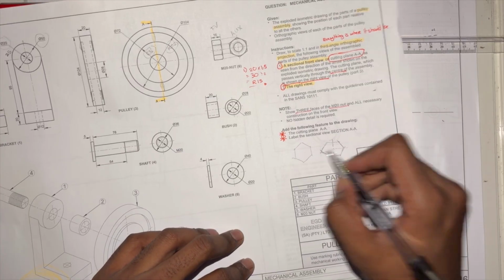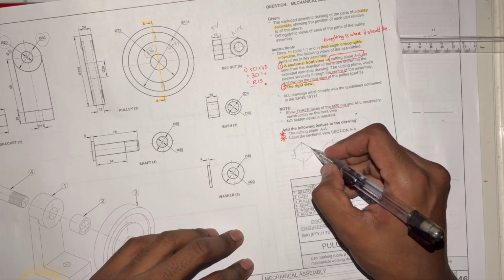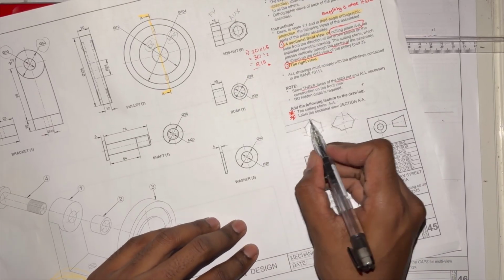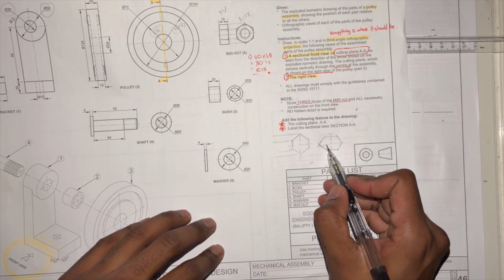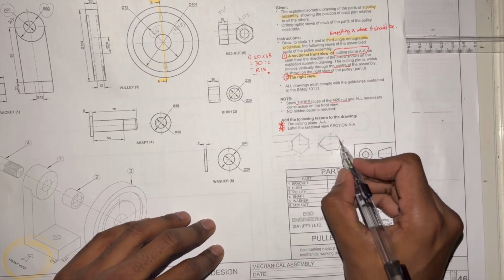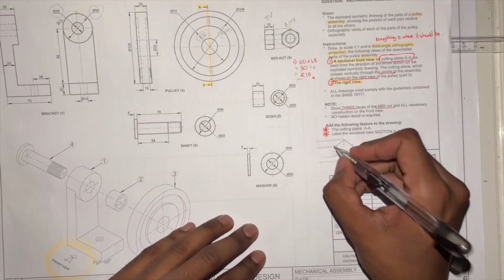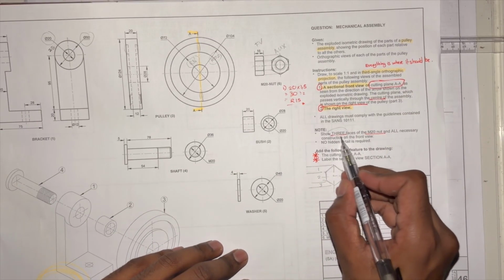Okay, no hexagon's complete without a nice center line. If you draw the hexagon this way and you're projecting to the left, you will get 3 faces. If you turn the hexagon on its side, the other way, you will get 2 faces. 1, 2, 1, 2, 3. That's how you determine whether you show 3 faces or 2.